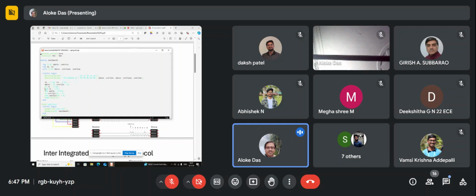Here you drive the signals, you add the values. RS means reset, control in, data in, and so on. You want to drive and see whether, in all possible cases that you can think of, the Verilog code is working fine or not. So this is how a test bench is written.